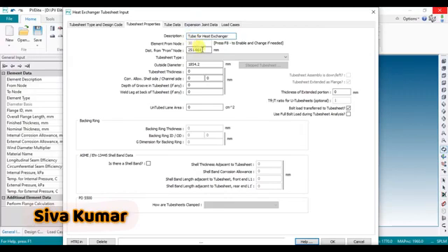And then here you see the distance from node. Okay. And then the tube type. So we can choose this as flange, extended as flange. Okay. Then outside diameter. Okay. Tube extended as flange. Pick this button, and then tube sheet thickness. We have to enter this.